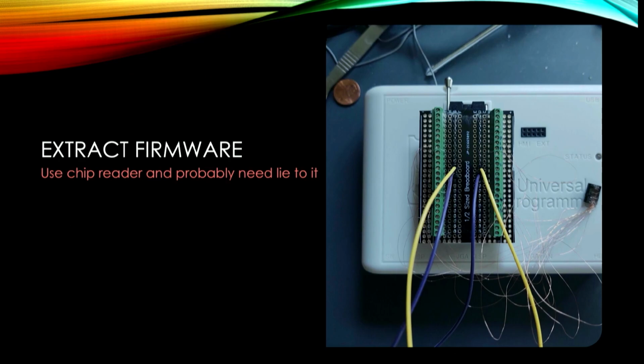But one thing kept throwing me, it wouldn't read. So I went back to, not the data sheet, but the pinout, the structure. It showed it, and it actually lists VCC1, VCC2, VDD1, VDD2. Turned out, even though the voltages and the ground were typically acceptable common, they were not common inside the chip body. So that's where those jumpers are on that particular one. So I just jumped it out on my chip reader to lie to it and added two new wires for each side of that to make that happen.